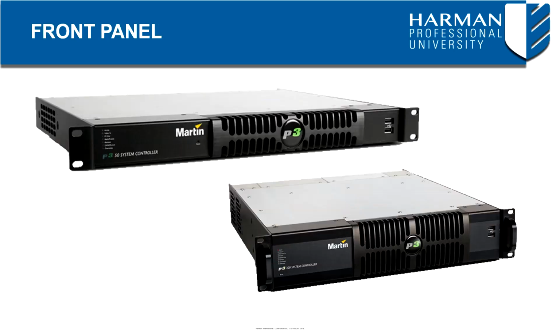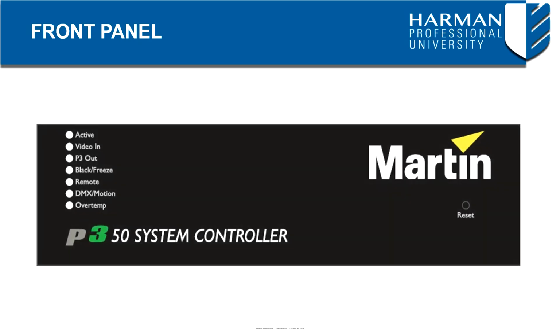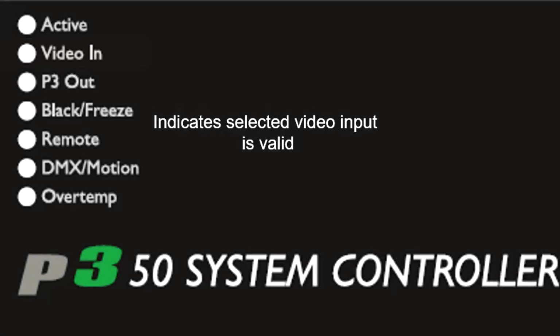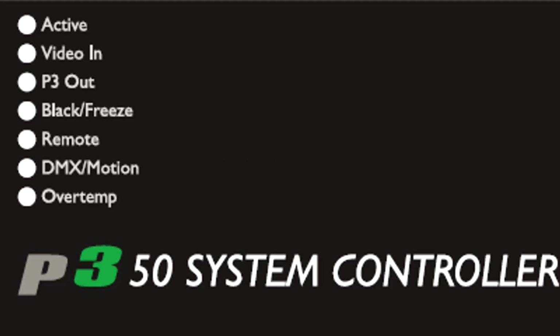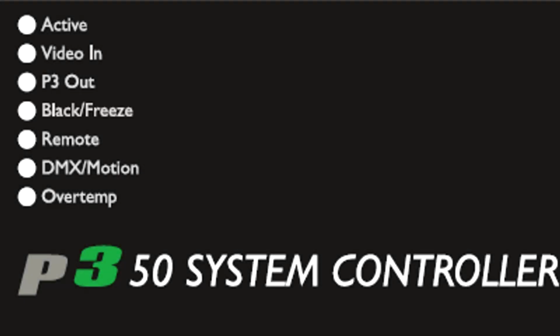The LED status indicators, reset button, and USB ports on the front panel of the P3 system controllers vary depending upon model type. They have the following functions. Active LED flashes during startup and lights continuously during operation. Video in indicates that the currently selected video input is valid. P3 out indicates the P3 system controller is sending a P3 data signal on its P3 output port. Black freeze indicates that a blackout or a freeze command is currently applied.